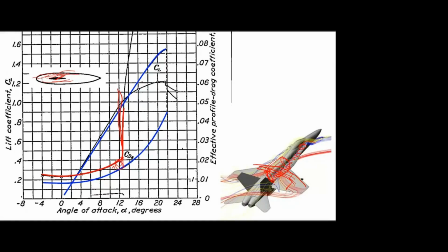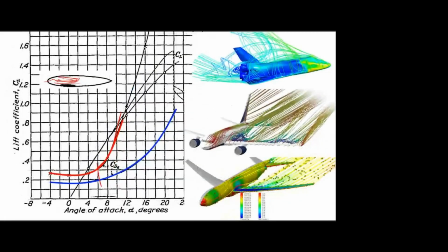Okay, so we cannot use fuselage space in this region. We know the main purpose of the aircraft is to accommodate more passengers and it should be economical. Okay, we don't see only the aerodynamic parameters. So if you go for the mid wing, all those main elements of spars and all pass through the fuselage. So this area cannot be used. So practically it is not feasible. So we are not going for the mid wing also. So mostly we are going for the low wing.